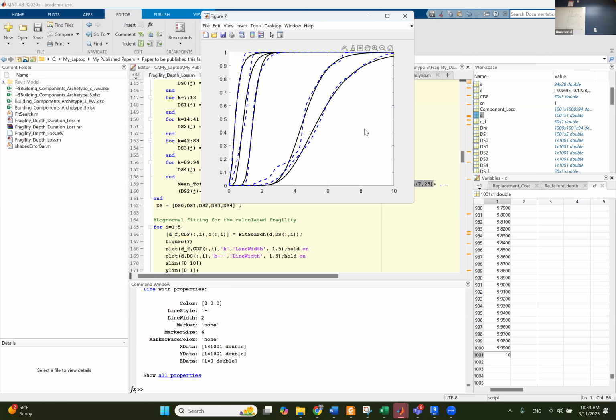The thing is, when we need to do analysis, usually we don't provide a line, because the way that we draw this curve, we had 1,000 numbers, and these 1,000 values of X and Y, we connected them and we made this curve. When we take this to research, we usually fit the curve, make the best fitting of the curve. So the next step, after I found out the fragility, I fitted them to a log normal distribution. We usually fit the fragilities to log normal.